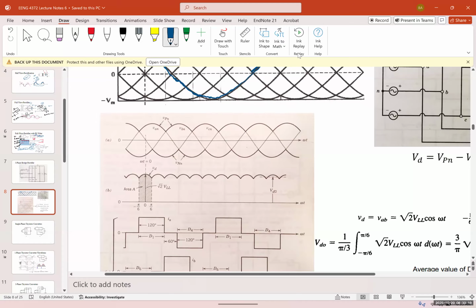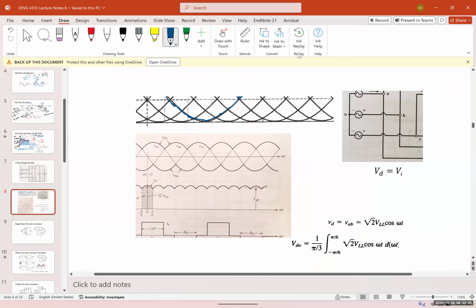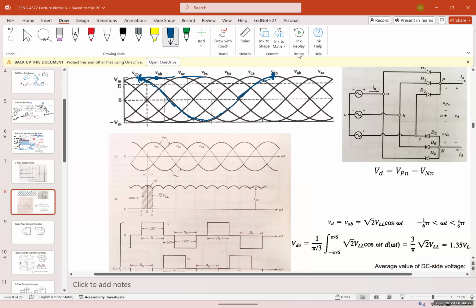Now for a 3-phase signal, to convert it to DC, first we use obviously the bridge rectifier, and you can see that here we have just the peaks connected, and it doesn't even go to 0. You can see that it stops here and you have the pulsating DC. Without the capacitor, it looks very close to DC.